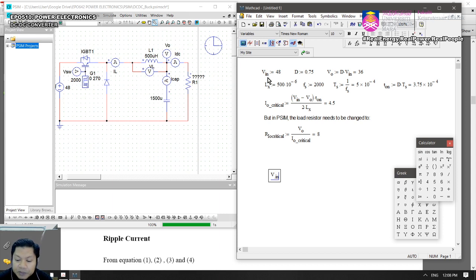If you want to assign a value or write an equation, just use the normal equal sign, and then you write the equation. For the subscript, you just hit the dot button, and if you want a superscript, for example 10 to the power of -6, you need to use the caret symbol, which is the button 6, the hat button.